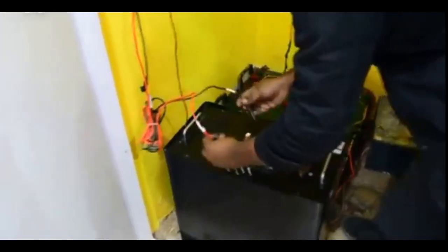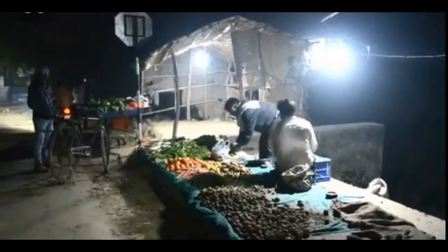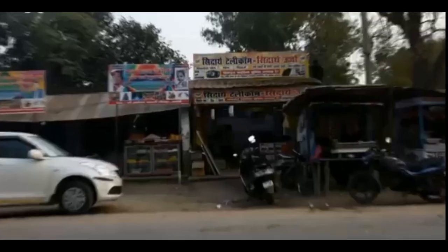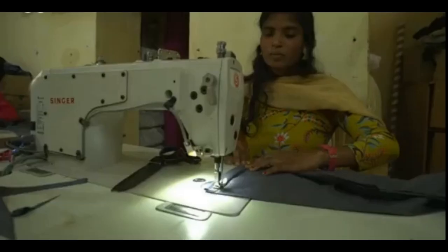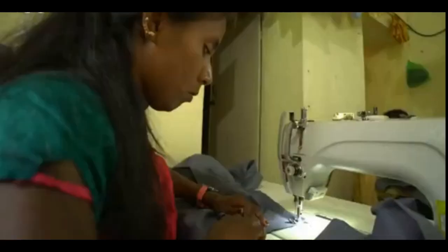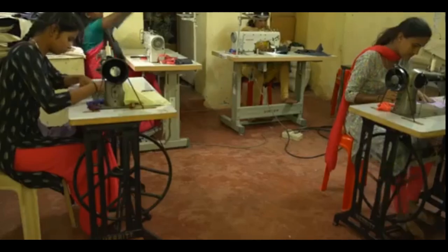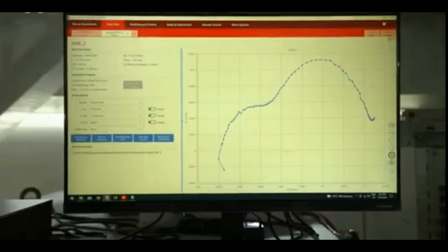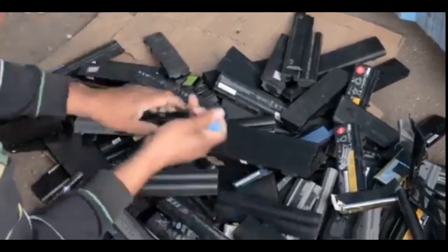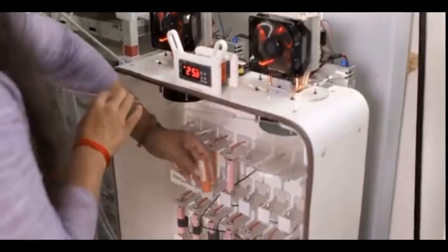or emergency response. It is important to note that the performance of used EV batteries may be degraded at differing levels depending on its past usage. Factors such as the number of charging cycles, storage conditions, and manufacturing quality can affect the remaining capacity and lifespan of the battery. Therefore, careful evaluation and testing are necessary to determine the suitability of a used EV battery for a particular application. Monitoring their performance, state of health, and remaining capacity over time is needed to make a methodical evaluation. A solid reason why these batteries must be tracked, together with their usage information.